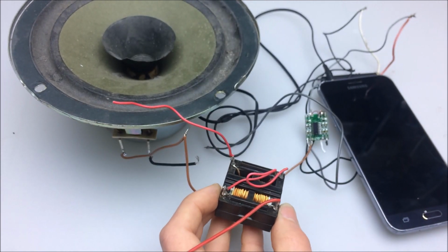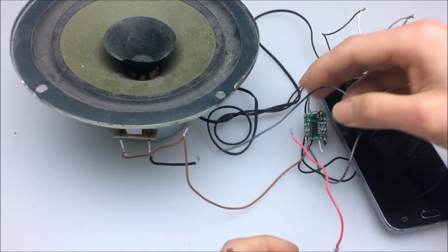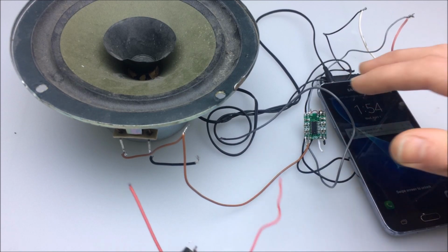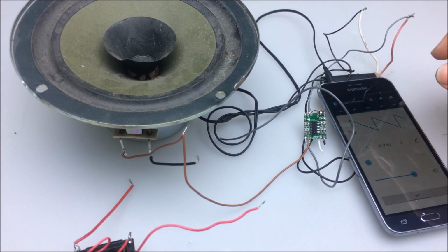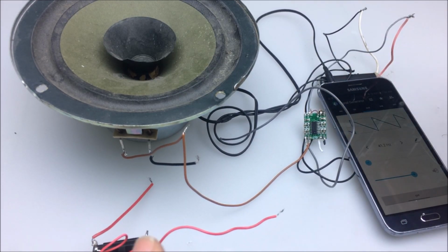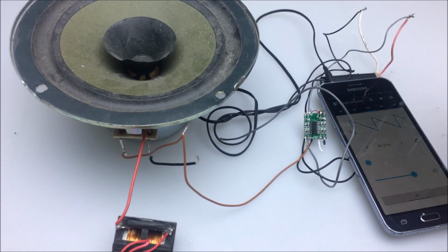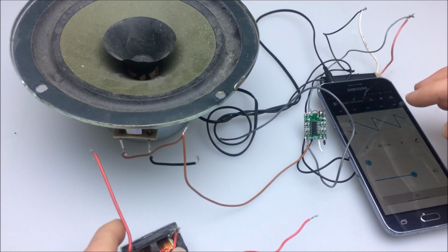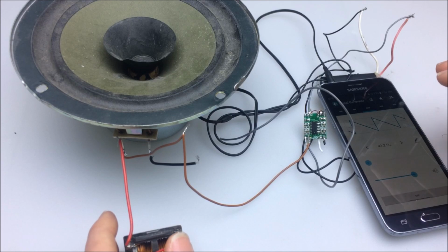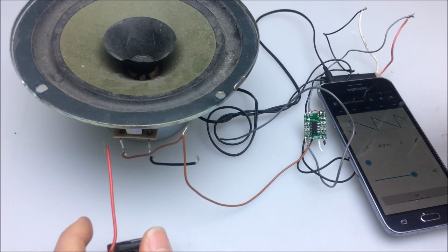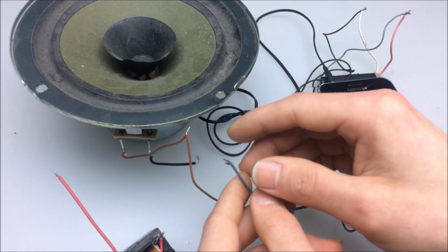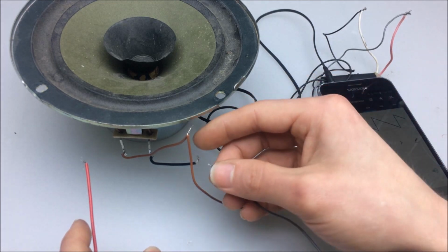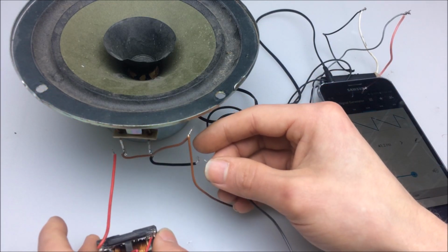Let me show you this in practice. Here I have the little amplifier connected up again, and I will do the same thing. I'll show you how the part has an effect on different frequencies. I'm going to be using a triangle wave, and it's about 40 hertz again. I'll hook it up and we can see the response that the speaker has on it without the loop flattener.